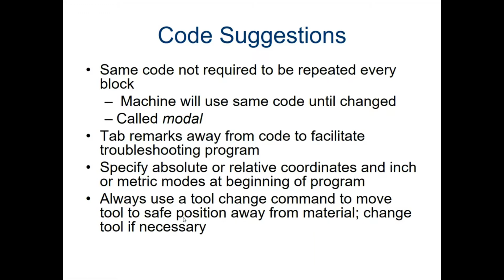Those things are held in memory and remember what that was from before. So when you're doing your programming and you're doing coordinates, if you're moving vertically or horizontally, I may not need to put the X coordinate, or I may not need to put the Y coordinate if I'm not changing those. I would say for right now, it's probably safer to go ahead and put all those coordinates in, even if you're not changing them, just so you don't forget something by accident. But you can definitely shorten up code, and that's what you're going to see when you get the computer generated code, that's what they're going to use.